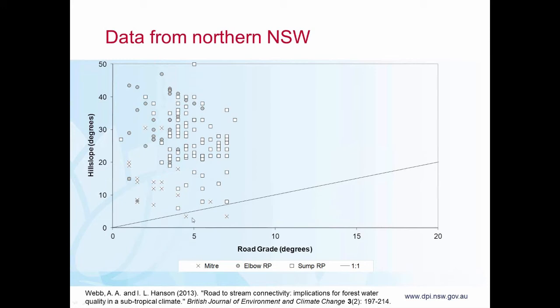We may have a very gentle grade in a road, which means that, under the former guidelines I talked about, it would be possible to space the drains a long way apart, but then you create the issue that if you're discharging water onto steeper slopes, they can be 30, 40, even up to 50 degrees in some places, then that water has the potential to create a gully. Typically this happens in side cut scenarios, that connects that drainage outlet with a stream and creates a problem.